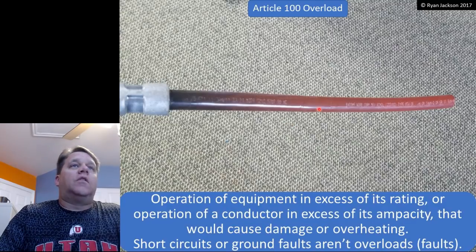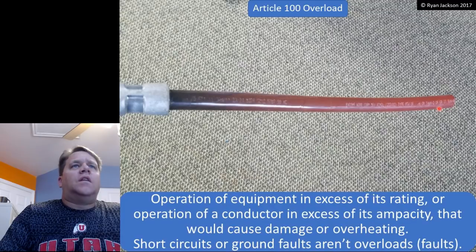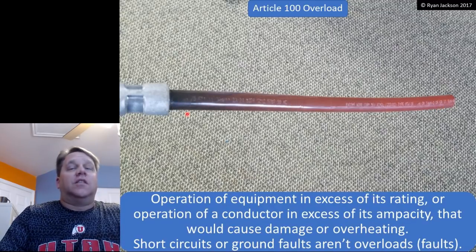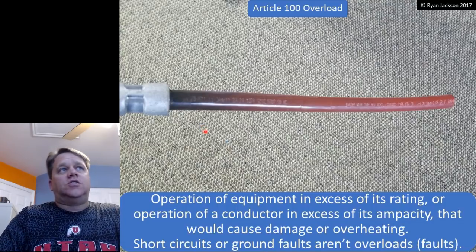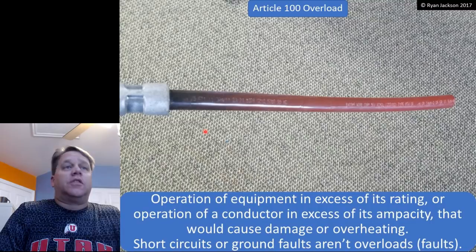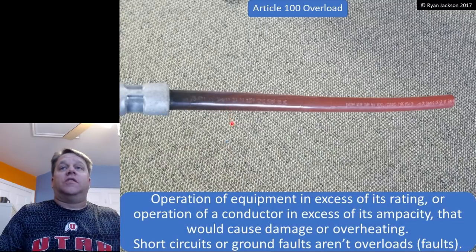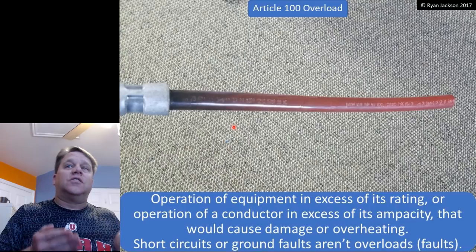Okay, so this wire right here, I know it's a little bit hard to understand what we're looking at here, but it was a brown conductor, and you can see that it has turned into a black conductor. That was the result of overload. This was at a place where I teach, and they had to change all of their transformers. This wire has an ampacity of 380 amps, but it was pulling about 600 amps. And as you can see, it's discoloring, it's melting, its insulation is failing, and ultimately it would have caused a fire. That's an overload, right?